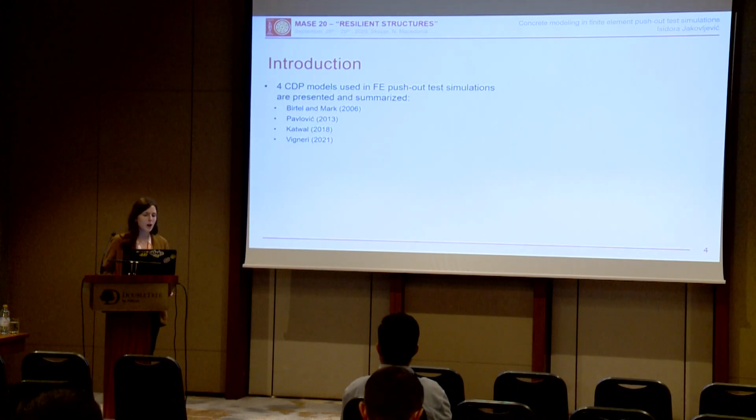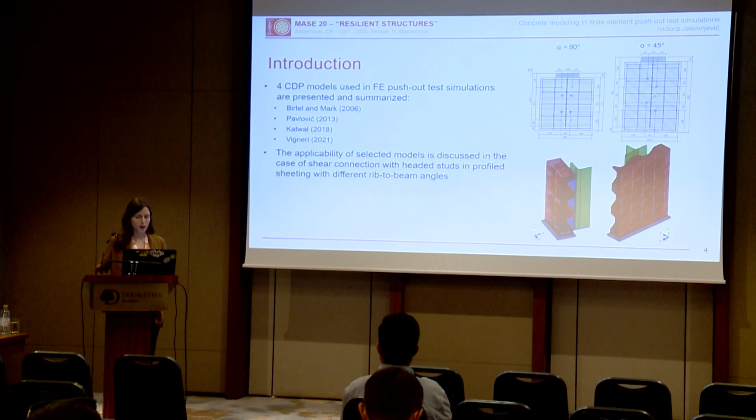So in this paper, we presented 4 CDP models that were successfully used in finite element simulations of push-out tests. They are mentioned here on the slide. Then we tested their behavior in finite element modeling of push-out tests with headed studs. We had 2 specimens, one with a rib-to-beam angle of 90 degrees, so the ribs are transverse to the beam, and the other where the angle between ribs and the beam is 45 degrees. But I will talk more about it later.